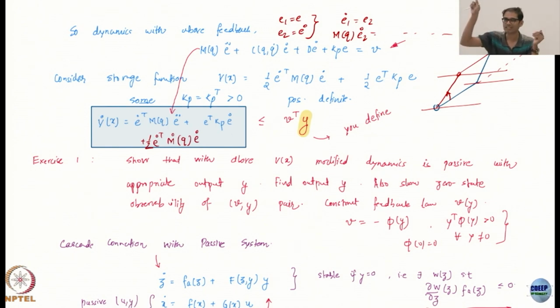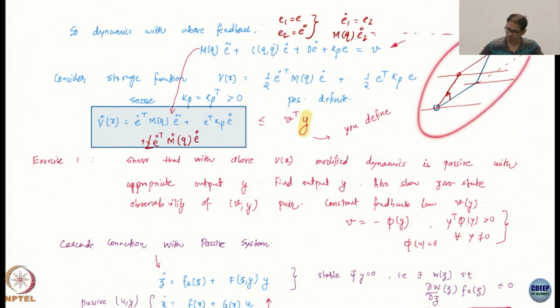But the fins, they have mass, right? And their location keeps changing with respect to the axis, and inertia is nothing but mass distribution. Your mass distribution is time varying. Okay, so if I write the inertia with respect to that fixed frame, my inertia is time varying or state varying. Yeah, it's not actually time varying, it's state varying. Just like that, more often than not, you will have state varying inertias.